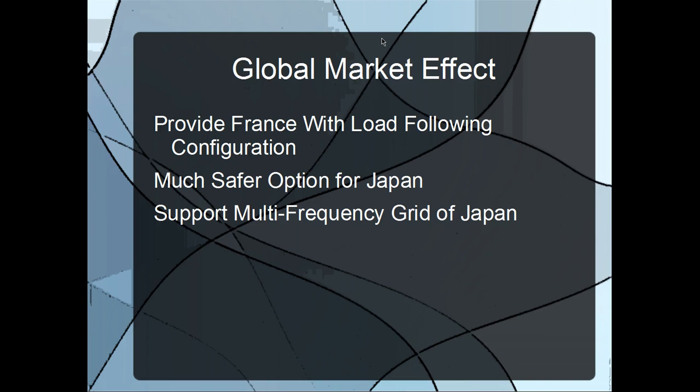This is beneficial in that each of the small reactors contains a small inventory of radioactive materials, thus limiting the potential damage in the event of a nuclear accident. In fact, NuScale claims to have a core damage frequency of approximately 10 to the minus 8 per module year, compared to a CDF of 2 times 10 to the minus 5 for U.S. plants as of 2008. This is attributed to the modular nature of the SMR as well as to its advanced passive safety systems that are capable of removing nuclear decay heat for extended periods of time without operator action or